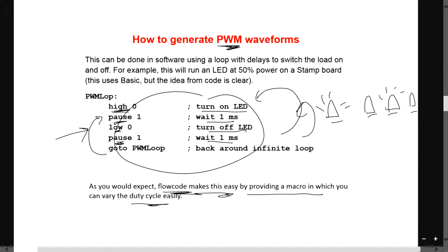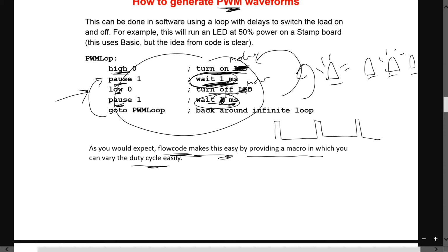So if you want a shorter power, you can turn on motor. In this case it's turn on motor, wait maybe 1 millisecond, turn off motor. If you want a low power, then wait for maybe 10 milliseconds. So you have 1 millisecond high, and then 10 milliseconds low, and then high again. You see? So this is a low power. So you can vary your waiting time for your high or your low, so that you can create a pulse width. That's just the meaning of that.